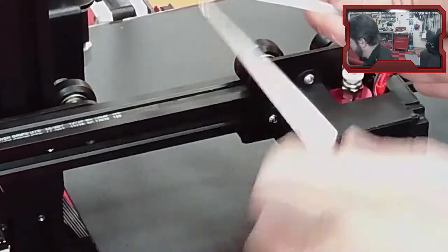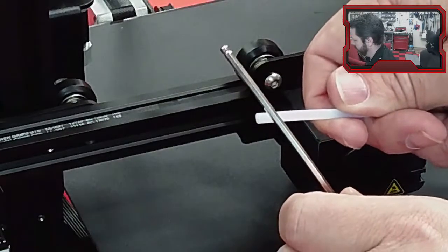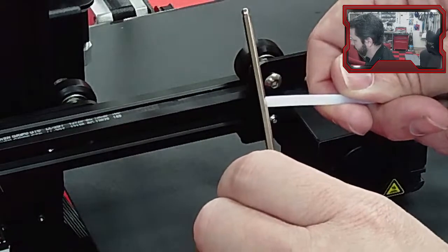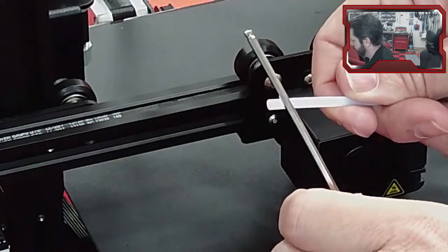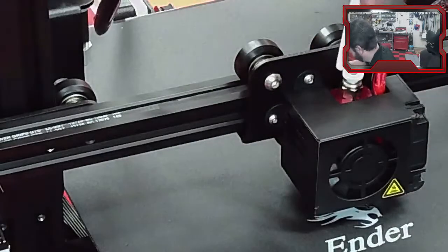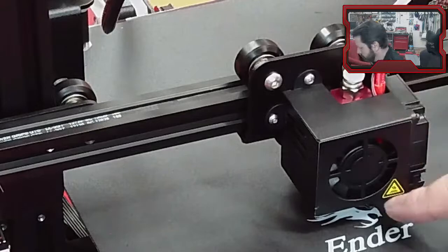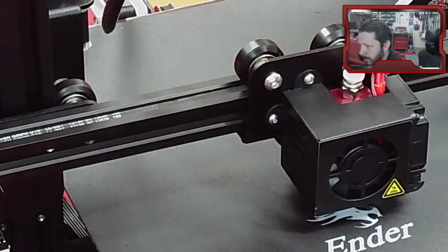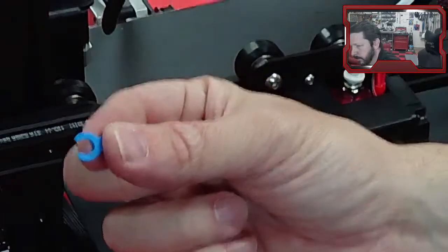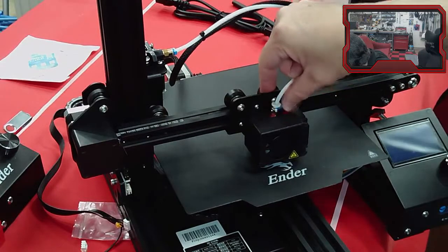Like the angle I'm talking about would be exaggerated, like if it was cut like that. That would be a really bad angle. This one's pretty close to being perpendicular to this tube, but it's a little bit angled. But make sure this is all the way in, seated all the way down till you hit a hard stop at the bottom. Otherwise, you're creating a gap between there. And then you put your little clip in there to keep it from backing out.